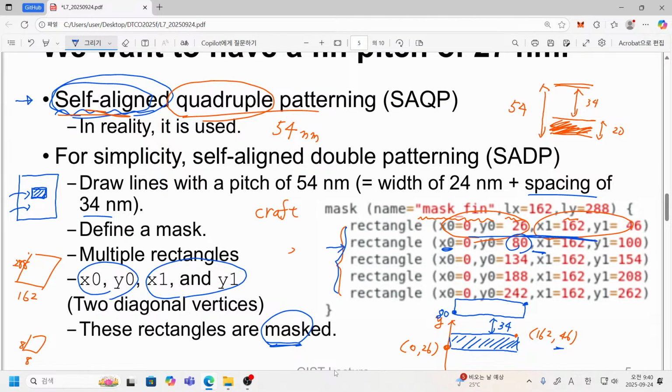Well, maybe you can ask me, why did you define it that way? How about the other way around, where the masked part is etched away and the unmasked one survives? It is related to the current popularity of positive PR. PR means photoresist. Positive means that when it is exposed to light, its chemical structure becomes weakened and eventually it can be washed away.